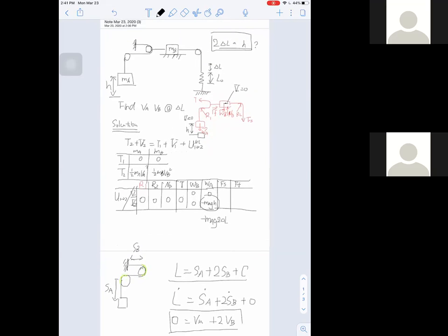Okay, then we can move on to the force from the spring, Fs. Fs is a conservative force. Therefore, the work done by it can be written as V1 minus V2. At position 1, everything is released from rest, so there's no stretch on the spring, so that's 0.